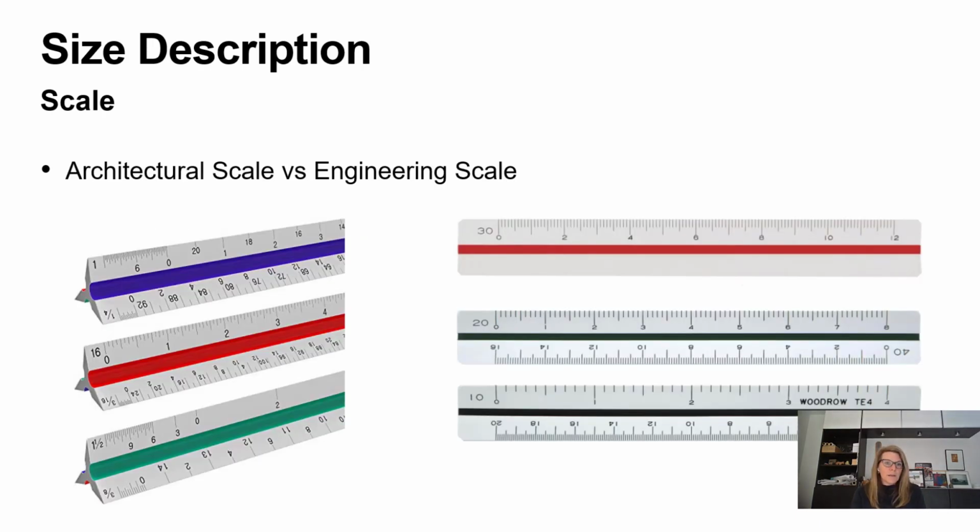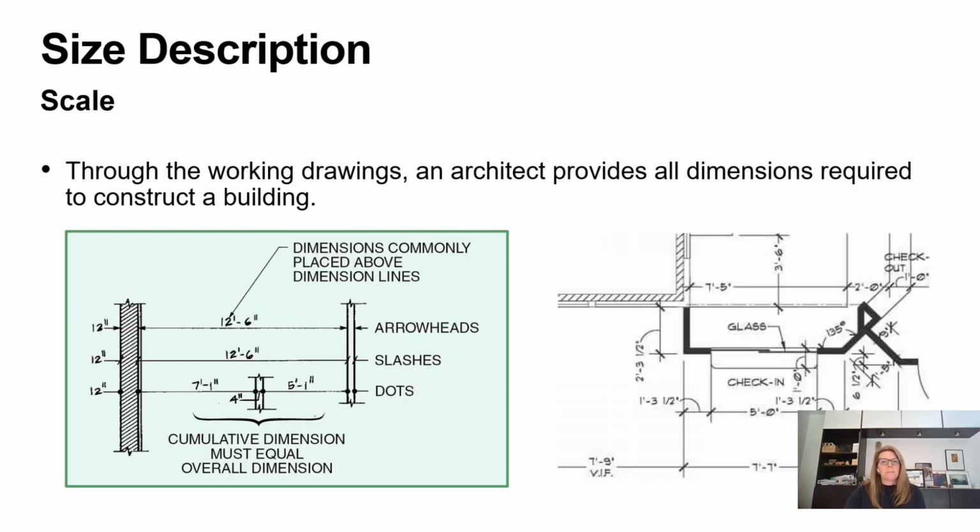So when we're looking at a set of drawings, generally the drawing should have all of that information. You should never have to scale, meaning measure anything on a set of drawings. If that isn't on the drawing set, then there's documentation that is missing. Again, you shouldn't ever have to use a tool to measure that information. It should be found there if it's been documented properly. So those should be provided as required.